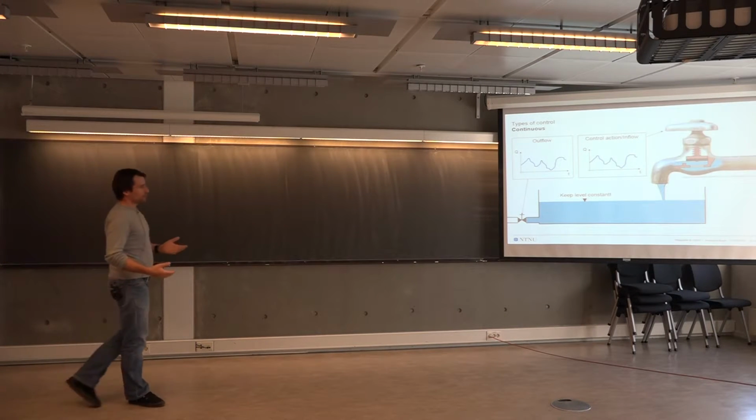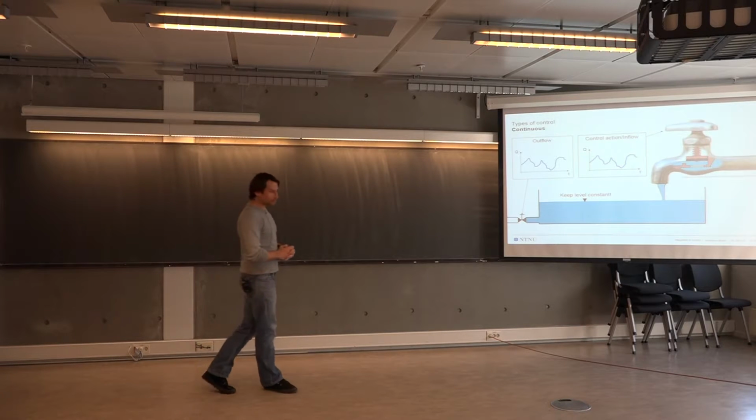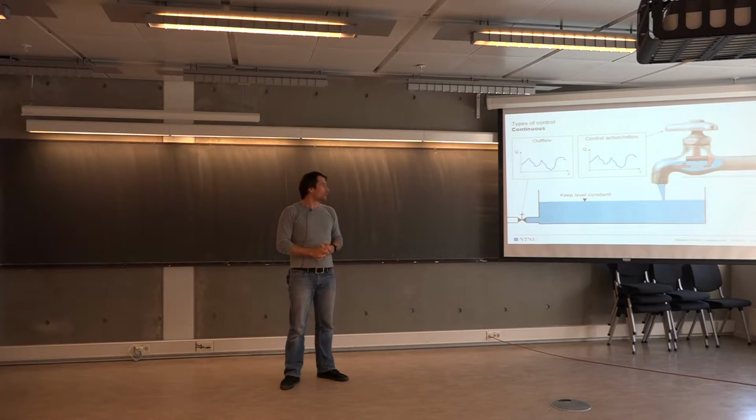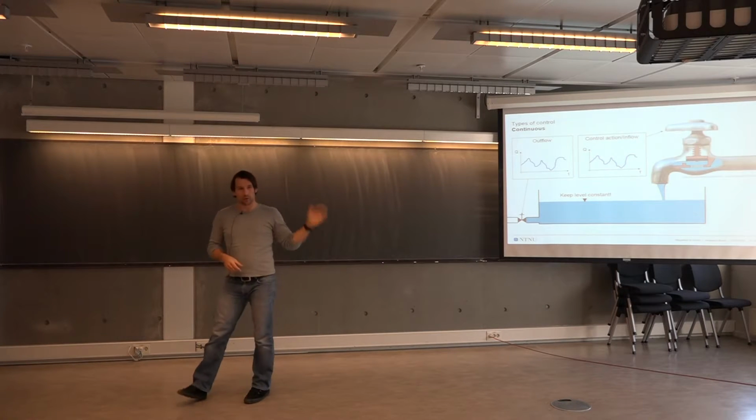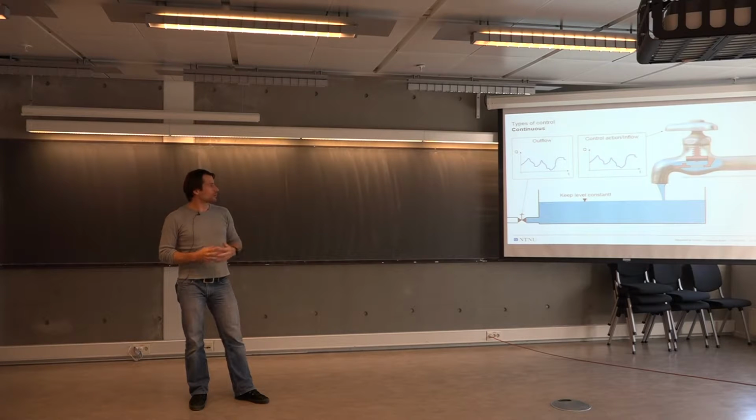Obviously, there's also continuous control. The difference now is, as this valve clearly shows, you can basically open and close that continuously, meaning that there's not just 0 and 1, fully closed and fully open. There are also states in between. So the control action, or the inflow profile which you can generate with such an actuator and a corresponding control strategy, control concept, is continuous over time.